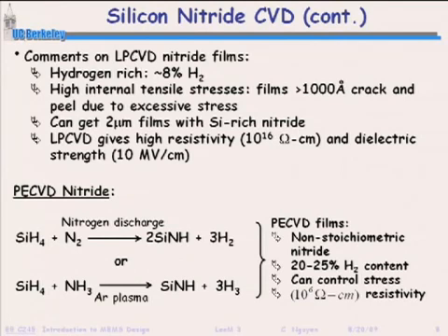So as you're doing research here, just keep in mind that this is not an industry foundry. You cannot plug your wafer into a certain tool and expect it to do what it says it'll do. You better test it first to make sure, because you don't know what the person before you was doing in that tool. And even the person before you with maybe a little bit of metal on their wafer before you came in, that could change everything for you.